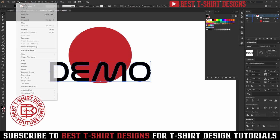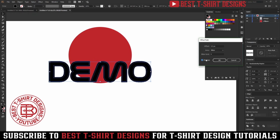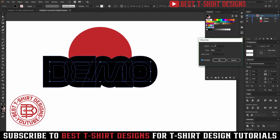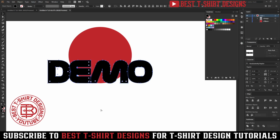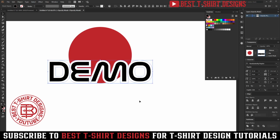So what we do, go to Object, Path, and then Offset Path. So offset path gives us this option to create an offset path like this. We can make it bigger, smaller, whatever we want. So let's say I want this style. So this is how it is going to be. We can cut it. Now we can select this shape, maybe open transparency, just like how you work with Illustrator, then press Ctrl F.